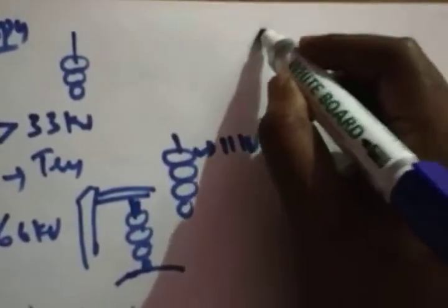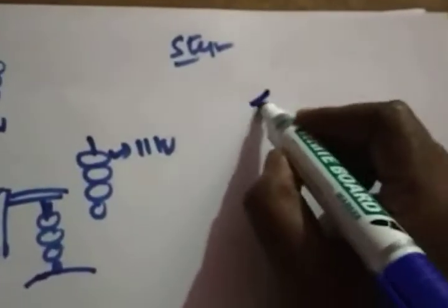And what is a strain insulator? The name strain is nothing but tension. At dead ends, river crossings or high places, there will definitely be tension on the conductor. In that situation we use strain type insulators. You can use them anywhere, from less than 11 kV to higher voltages. Less than 11 kV, the strain type insulators we can call a shackle insulator. One more concept is the shackle insulator.